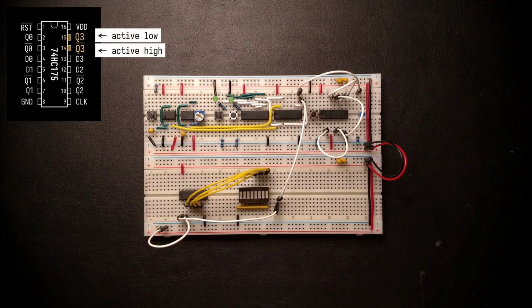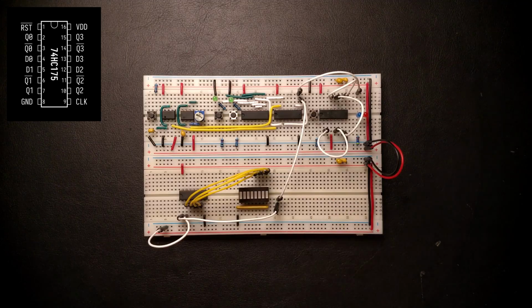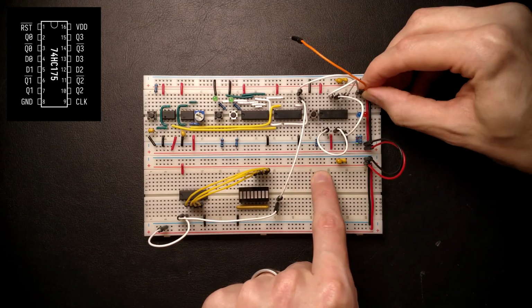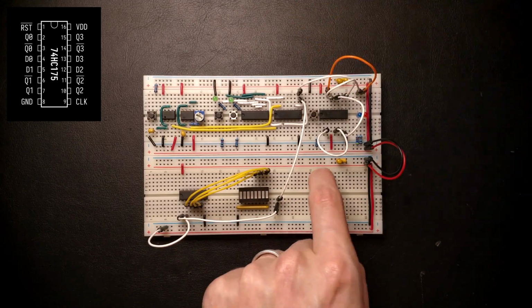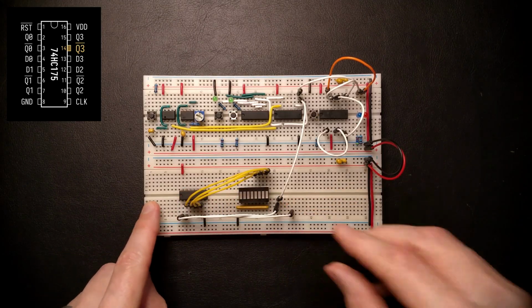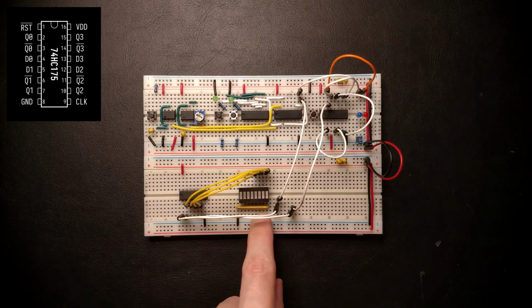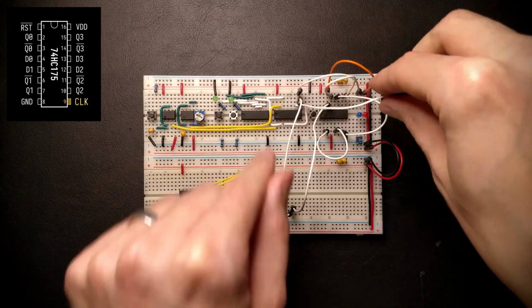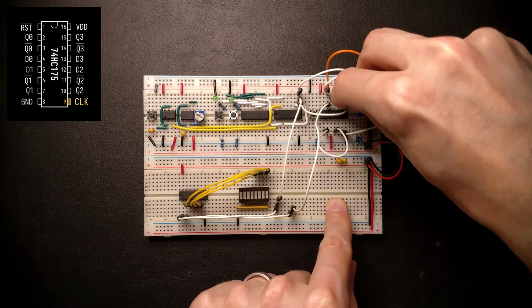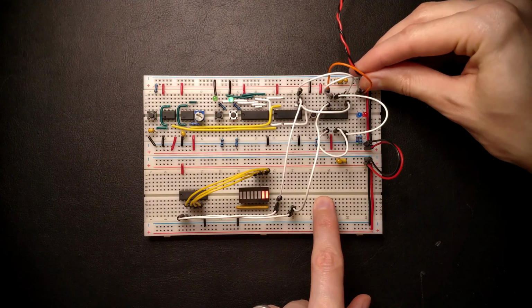The outputs of the last flip-flop are our synchronized reset signals. Pin 15 is active low and pin 14 is active high. Let's hook up an LED so we can observe the reset state along with the generated clock. Let's hook up our active high reset output to the counter circuit down here. And we'll also want to connect the clock input of the flip-flops on pin 9 to the output of the clock multiplexer. Alright, let's power this up and see if it works.